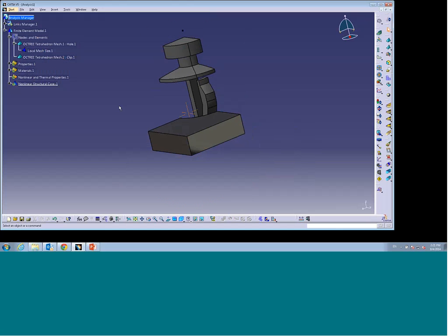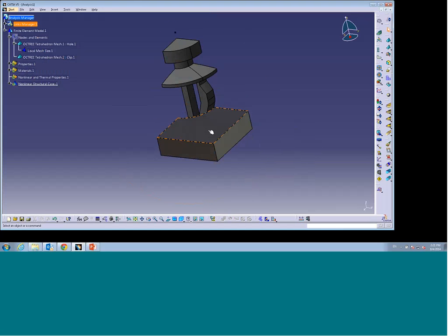Okay, so the steel panel is made of steel, which has Young's modulus by a couple of orders of magnitude greater than the plastic. So what I can do for efficiency is actually make this part as a rigid body. And I'll use what is called the rigid body constraint. I didn't have to do it, but for efficiency, as I said, the rigid body constraint simplifies computations and the analysis just runs faster.